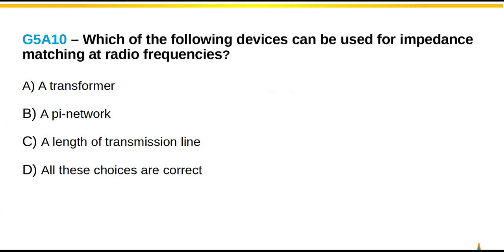But that prime power rating is for the whole radio, not just the power amplifier. Well, true, but usually the other parts of it, when you're not transmitting, you're only going to draw 1 or 2 amps. That difference would be the RF portion of it.